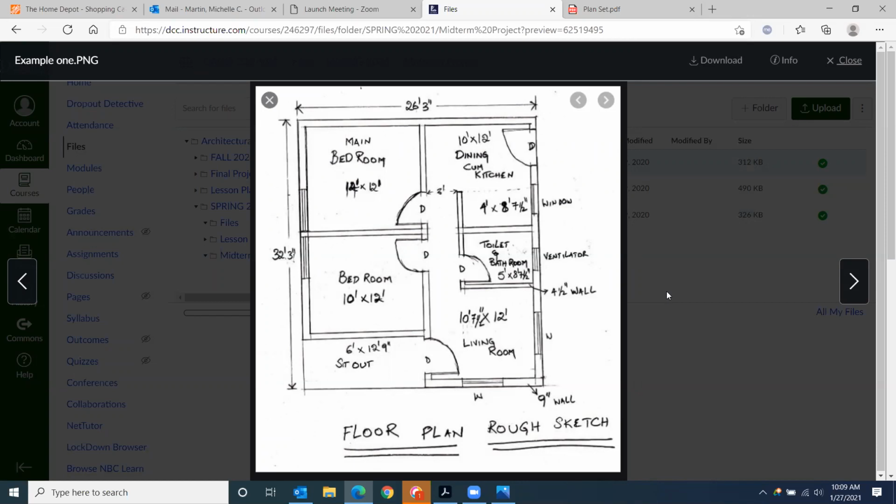Some of your older houses, those walls may be a little bit thicker because of the dimensions of the wood at that time. People talk about 2x4s, which is the main lumber that creates the walls of our house. The actual dimensions of a 2x4 are 1.5 by 3.5, whereas some of our older houses had true dimensional lumber, which was an actual 2x4.